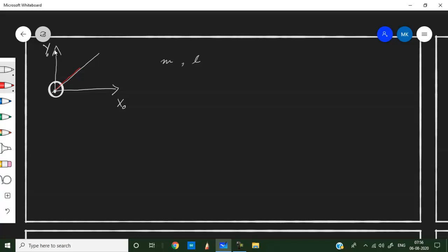Along the axis of the joint, that is this one, out of the paper or out of the board, it will be Z1, and this can be taken as X1, and this will complete the right hand. As per the right hand convention, this will be Y1. All right, which in turn defines this as theta, or you can say theta 1 in this case.